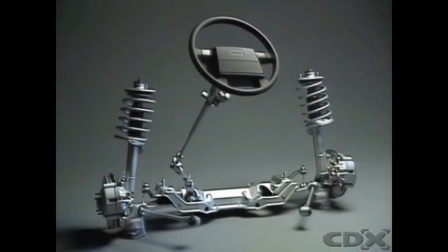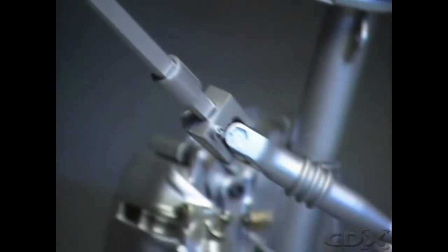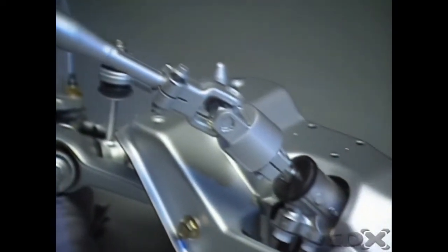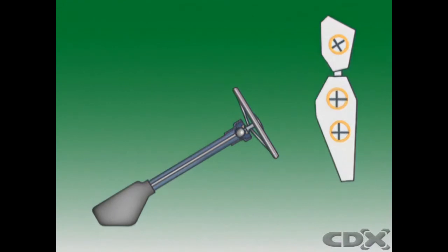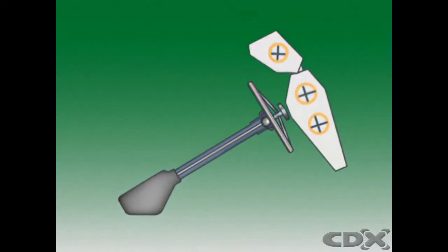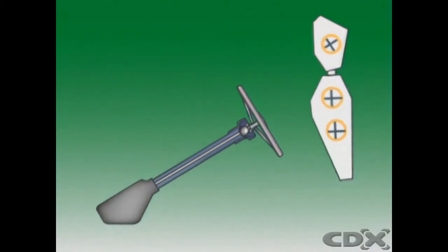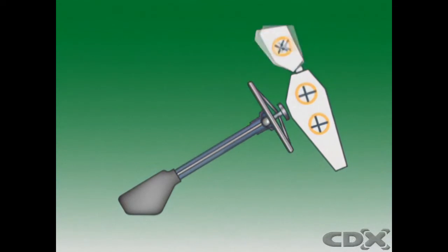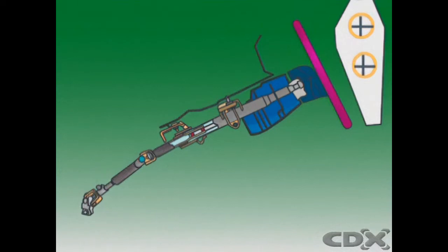Effort applied to the steering wheel is transferred down the steering column or shaft to a steering box. In early cars, the steering column was a straight shaft running inside a hollow tube. The steering wheel was attached to one end and the steering box to the other. In many frontal collisions, however, this caused serious injury to the driver, partly because it was forced back towards the driver's head and partly because the sudden stop forced the driver onto the wheel. To reduce this hazard, some steering columns are fitted with collapsible sections that protect the driver.